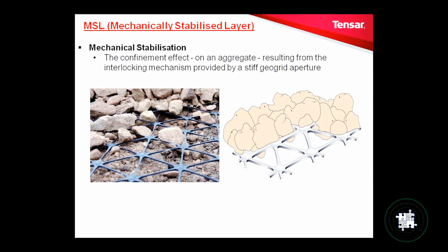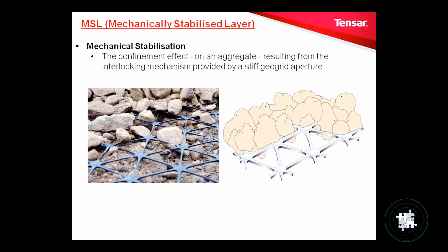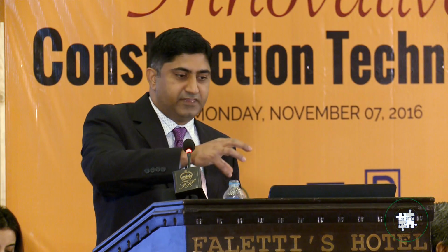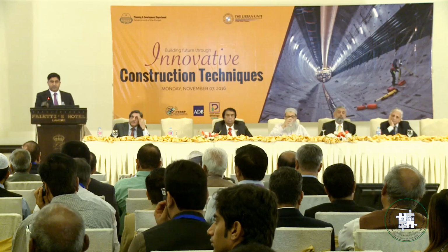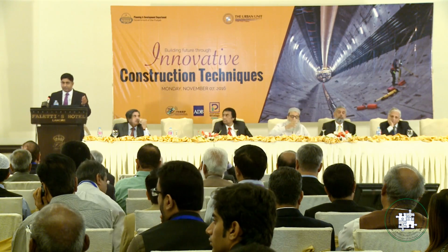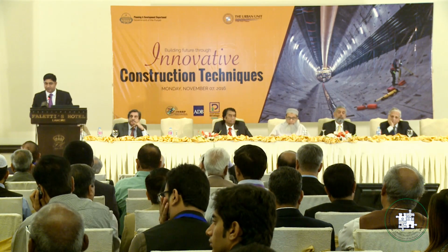From all this research work, we developed a concept called mechanically stabilized layer, or simply MSL. This is the same concept: the grid interlocks with the aggregate and forms a composite structure. Like Dr. Sohail Kibriya mentioned, there is some similarity with the RCC structure.